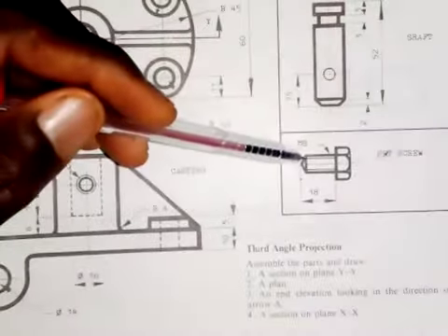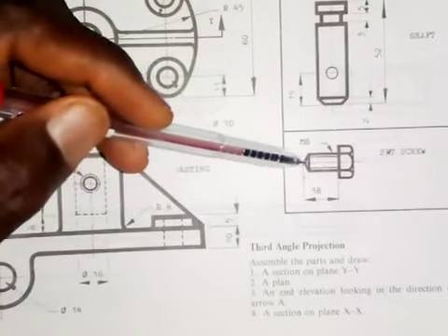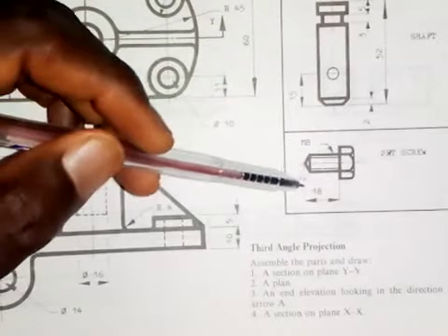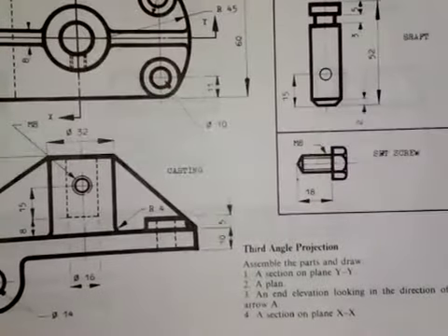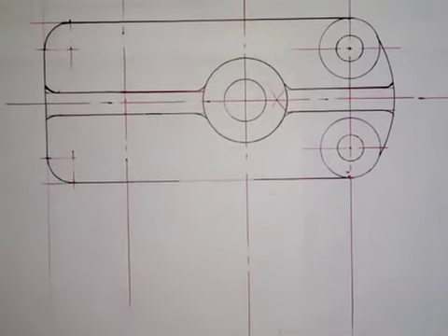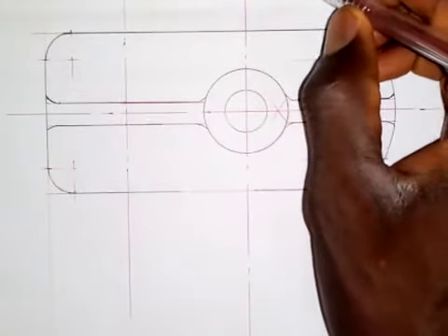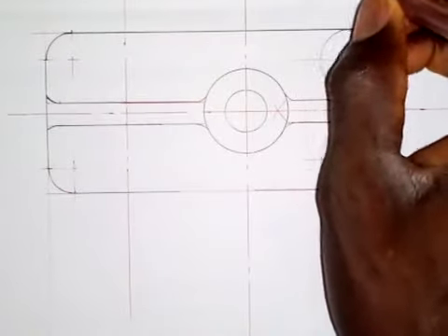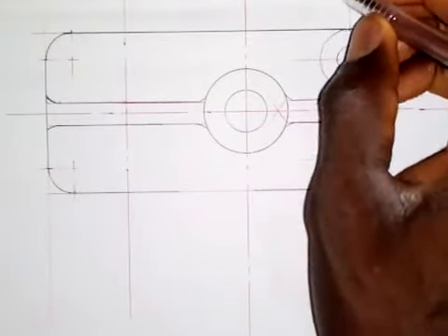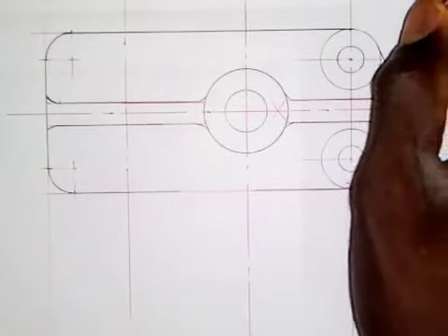So for the set screw, the thickness here is 8 millimeters, and the distance from here to here is 18 millimeters. And then here, the thickness of this hexagonal head is not given, but we need to do something. We have to do a simple calculation. If you have watched my video on how to construct the front elevation and the end elevation of a nut, you'll know what I want to do here. So we are going to make use of the formula, which is 1.5 times d, where d is the diameter. So this will be equal to 1.5 times 8, and this is going to give us 12 millimeters.